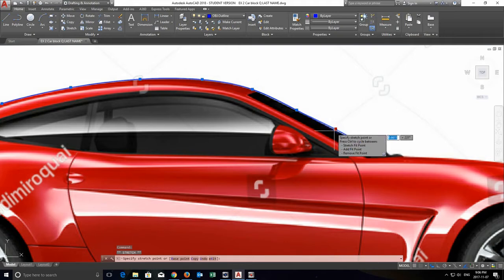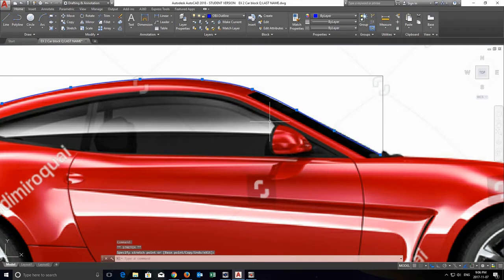Now, you might be tempted to make a whole bunch of lines or a whole bunch of clicks and have a whole bunch of control points. That's not a good idea. The more control points you have, the more bumpy your line is going to be. The harder it'll be to smooth out. The fewer control points you have, the smoother your line will be, but the less control you have over it.